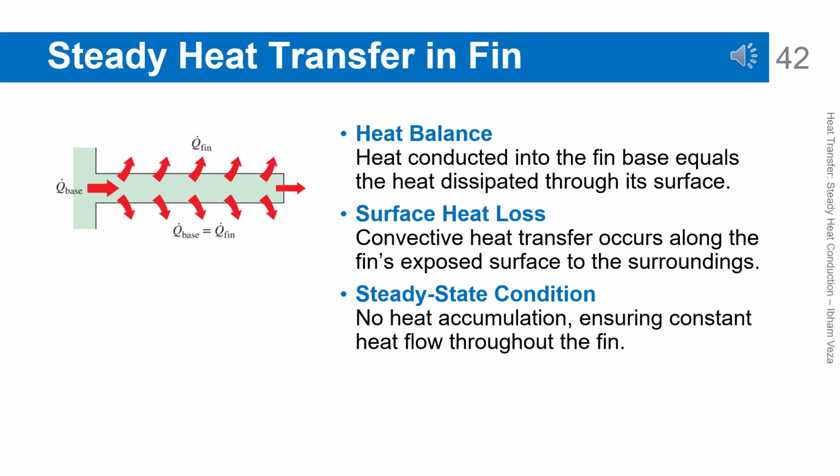Steady heat transfer in fin. Under steady conditions, the heat conducted into the fin base must equal the heat dissipated from the fin surface. There is no energy accumulation inside the fin. Heat loss occurs continuously along the surface by convection. This ensures that the heat flow rate inside the fin decreases along its length. This energy balance principle forms the basis for fin performance evaluation.